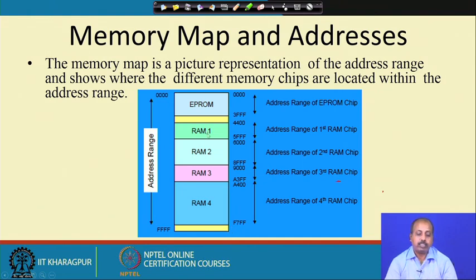In the rest of the places I have RAM, and since we cannot change the content of EEPROM, we cannot write onto it unless it is accepting the programming part. So, you should not try to write onto the EEPROM part. You should only read. Once this memory map is known, the operating system can introduce those checks and the error checks and all that.